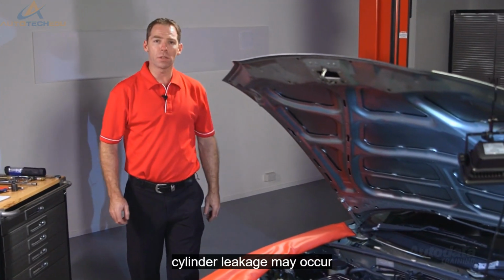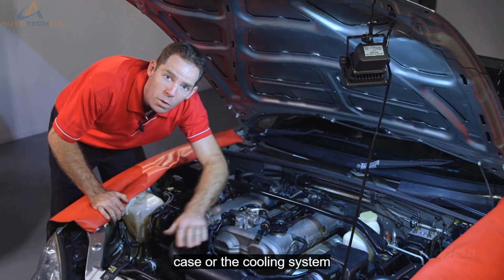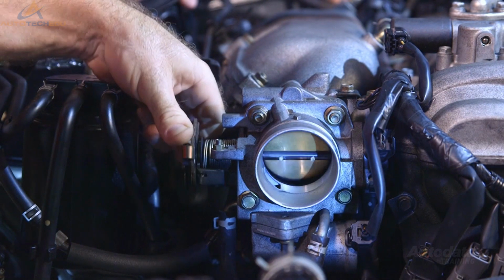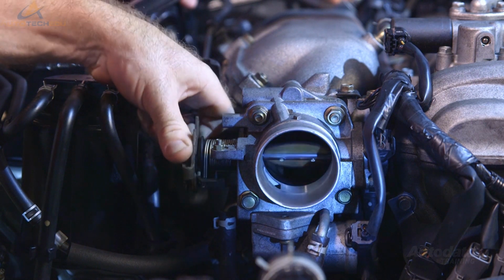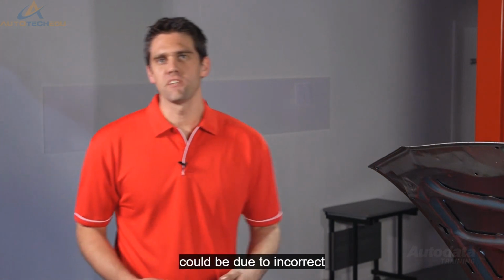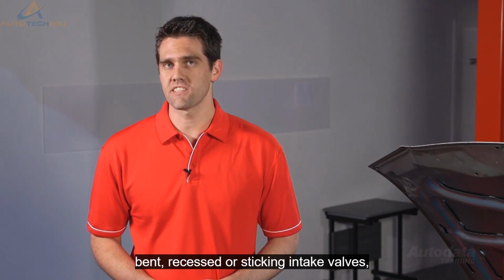There's 4 places cylinder leakage may occur: the intake valves, the exhaust valves, the crankcase, or the cooling system. If high leakage is evident, open the throttle valve and listen for escaping air. If air is heard or felt, then the intake valves are the likely cause. This could be due to incorrect valve clearance or timing, carbon buildup, burnt, bent, recessed or sticking intake valves.